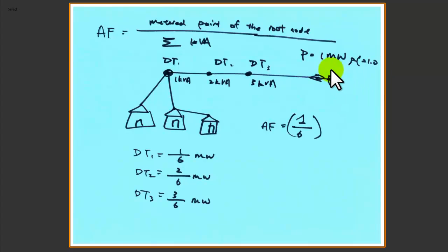So in this case, you have to watch out for the unit here. I don't think I mentioned it during the class today. If you have this in K and this in mega, you probably have to scale that by 1,000 times. So if I may correct this a little bit, I will have this 1,000, and then this will be 1,000. That can change it to kilowatt. However, if you want to use it in a megawatt unit, you can actually use the version that I had earlier. So depending on your preference of unit, you can use either. As I said, most of the time after the distribution feeder all the way to the consumer, we usually use kilowatt, the K value, instead of the M value, right? So I just want to point this out so that you are aware of the consistency.